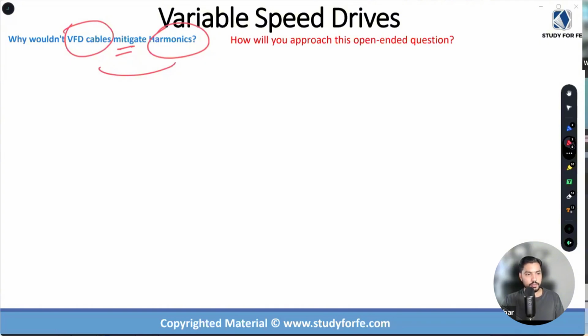Not really, right? That's your last line of defense. And we discuss in NFPA 70E in a lot more detail the hierarchy of different types of controls, right? Mitigation would be when you are able to do substitution. Mitigation would be you install some sort of engineering design, right? You tune up or tune down your protective device coordination. So you're actually reducing the amount or the source of the trouble.